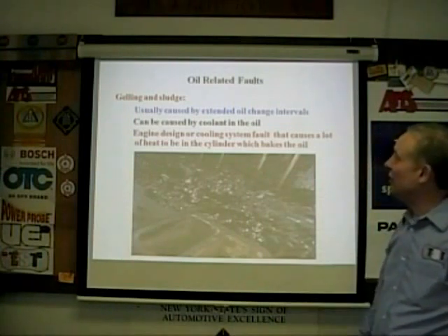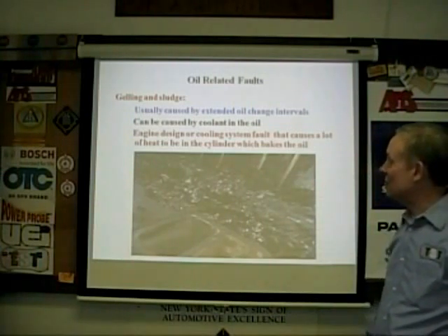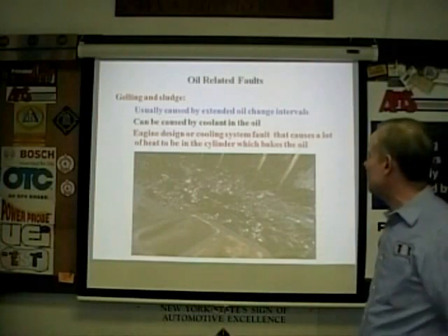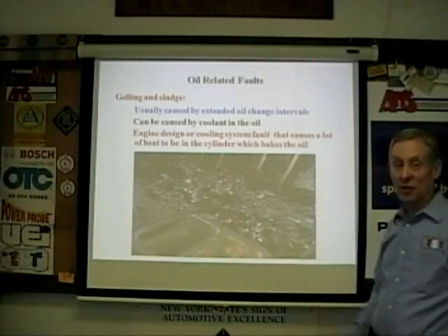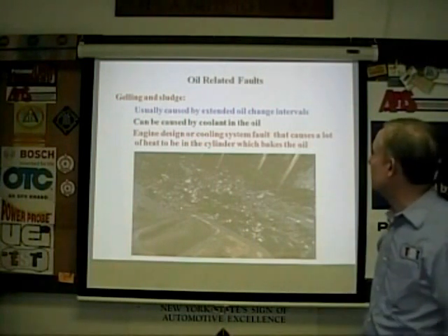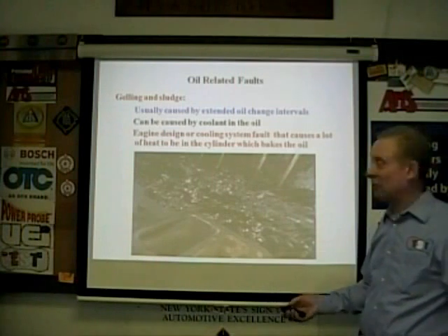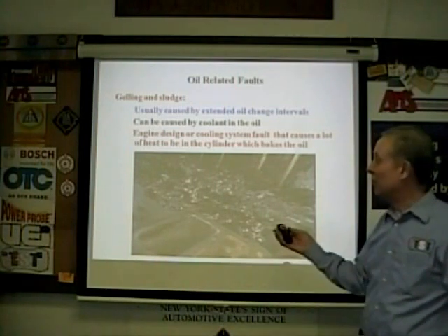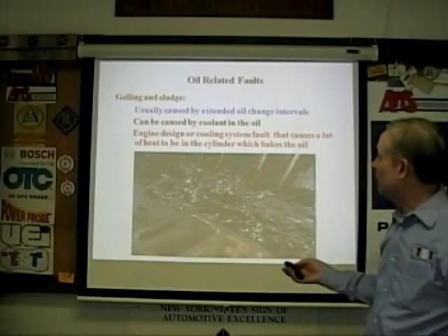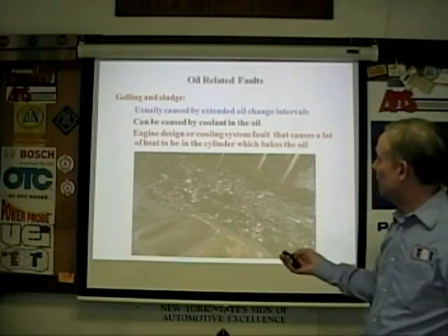Okay, oil-related faults, gelling and sludging. Usually caused by extended intervals. One of the many reasons I don't like to do this. Can be caused by coolant or other contaminants in the oil. Engine design or cooling system faults. Obviously, if it's overheating, you're going to have a much bigger tendency. If you have PCV problems, you're going to have a much bigger tendency to have gelling and sludging.